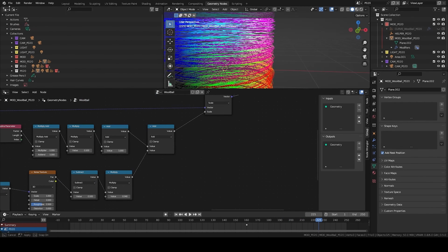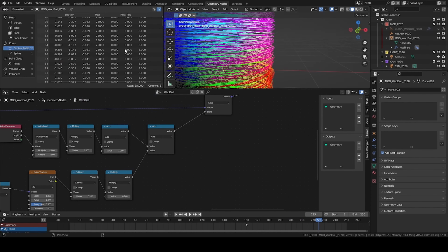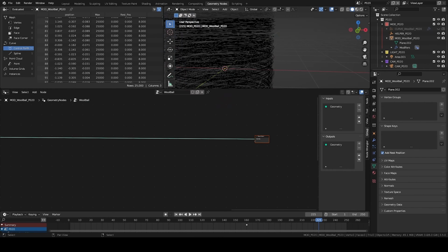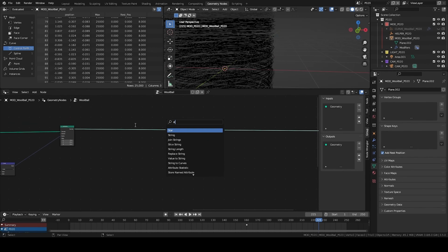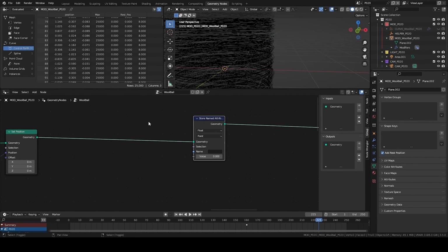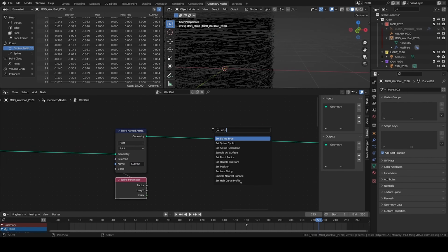Let's keep going. I'm going to keep the spreadsheet visible. I move the viewer, and now we start building the animation system. So for that, I first store an attribute that I call curve view, it's Houdini's priority, but it's the spline parameter, so I don't have to recall it afterwards, knowing that my curve is going to change size. So I add a spline parameter. Put it in the attribute, and I call it curve view. It's an attribute that is on the points.